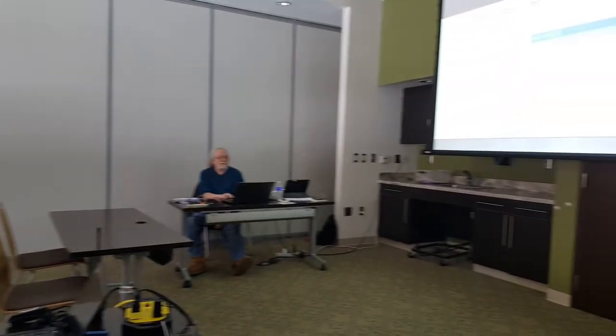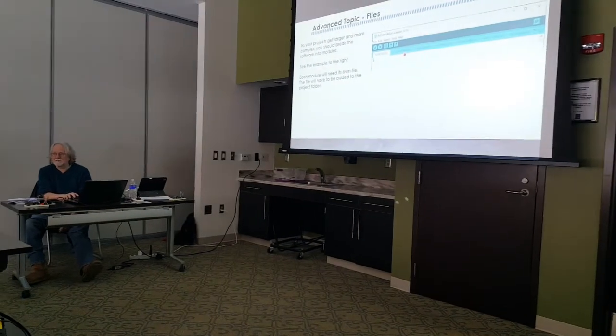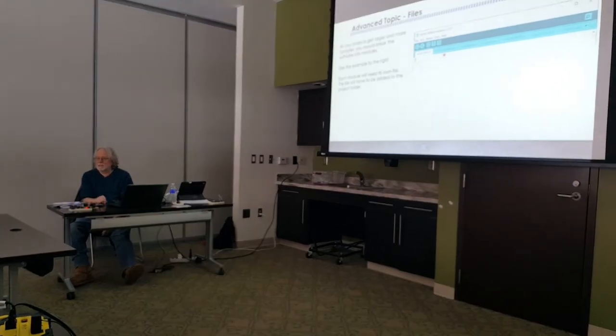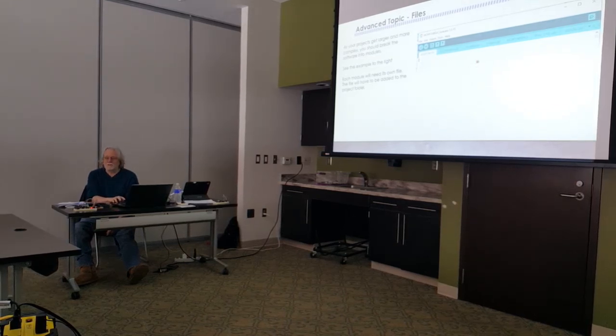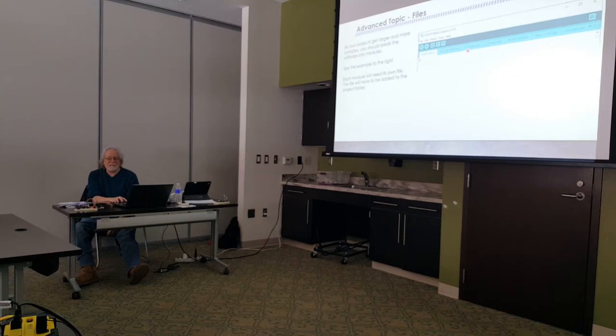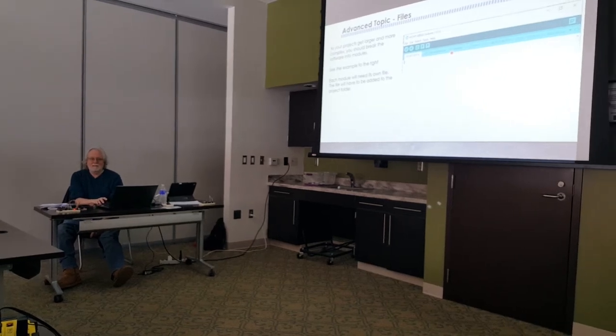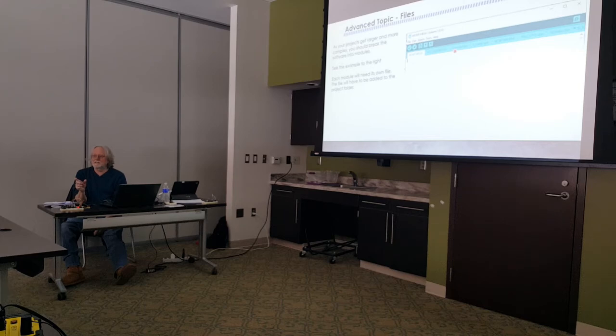So here, I put an article in, I broke it down, so like this tab here is the code practice oscillator, and it's nothing more than: close the key, it turns the buzzer on, and release the key, it turns the buzzer off. So there's some code for that. And then you get to this, which is a decoder. Actually, you put a tone detector in front of the pin on the processor, so you get a 1 when the tone's on and a 0 when the tone's off. So I can hook the tone detector up to your radio, and this will decode the Morse code that's coming in.